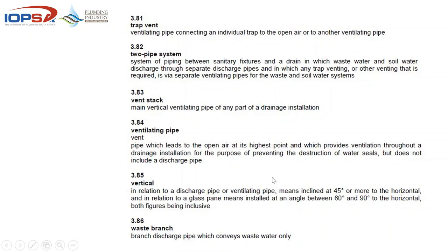Vent pipe, a couple of requirements on that, there's another YouTube video on the LMS. You guys can look at venting there. There's 7 or 8 requirements with regards to venting. So a vent pipe would lead to open air, not a little puff pipe that ends up in a building or in a specific little enclosure. Open air is the requirement.